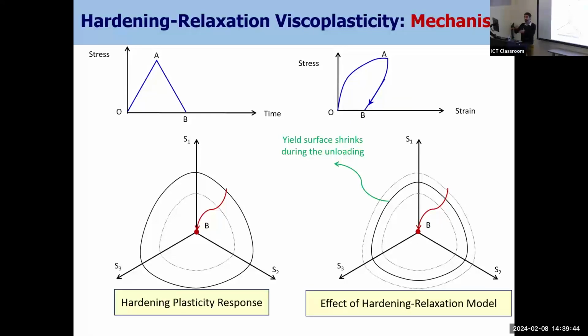Their issue was that at some point the hysteresis loop stops moving, and they use what is called a memory surface, but in the stress space, to define that. For our case, we are doing something very similar, but in the plastic strain surface.